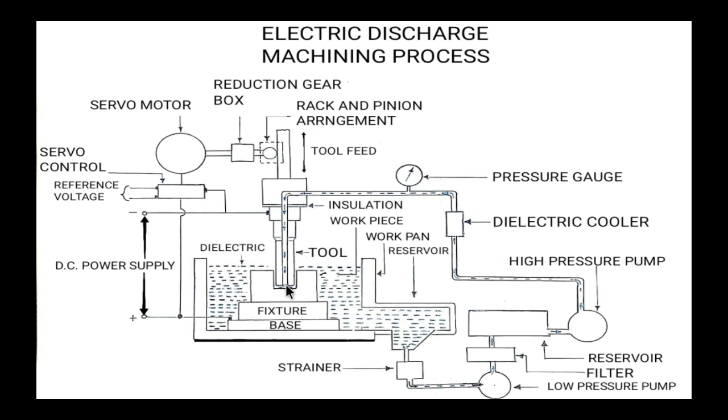So, let us discuss the working principle of the electric discharge machining process. With the application of voltage of about 50 volts to 450 volts, electrons start to migrate from cathode to anode. Hence, an electric field builds up between the two electrodes at the position of least resistance. The ionization leads to the breakdown of the dielectric, which results in a drop of voltage and the beginning of flow of current. A column of vapor begins to form and localized melting of the work commences. The discharge channel continues to expand along with a substantial increase of temperature and pressure.